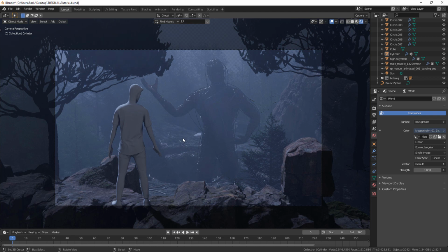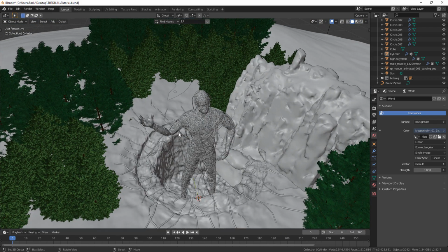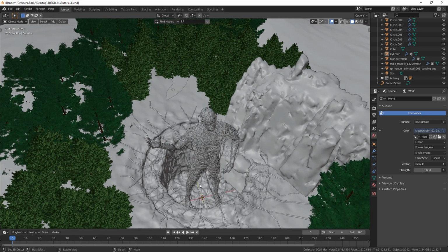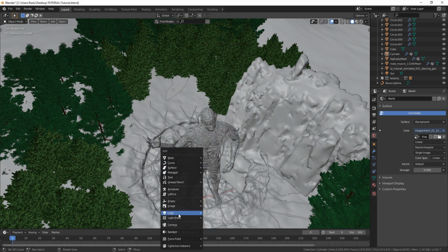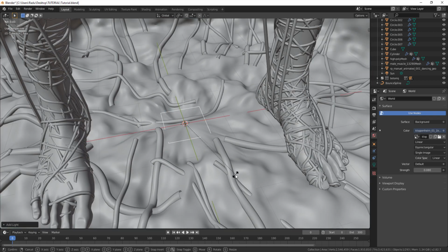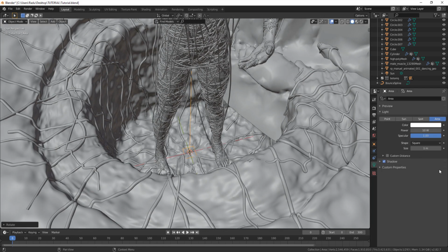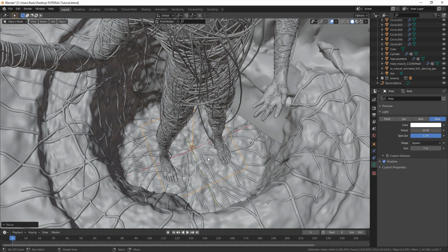Now, what I want to do next is add the light from the fire. So simply add an area light, turn this 180 degrees to be facing upward, make it bigger, but let's make it bigger from here. So 5 meters, 7 meters, bring it up a bit.